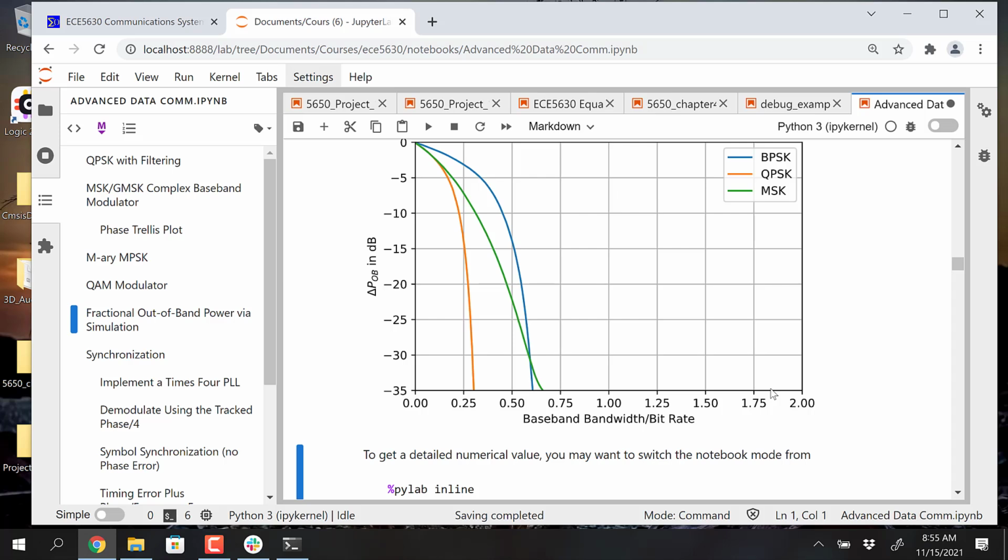At any rate, now you see that pulse shaping is very bandwidth efficient, but we knew that from the get-go. That's why it came into vogue for digital comms. We can control the ISI to not exist at the symbol sampling points, and we can get a very compact spectrum. And we can change it slightly by modifying beta or alpha. Remember, beta and alpha are just two different symbols used. The book uses one, my code uses another one, but so that beats out GSM. But